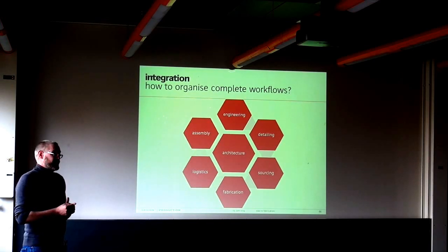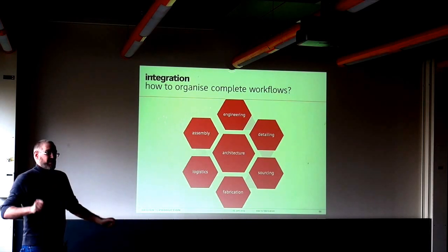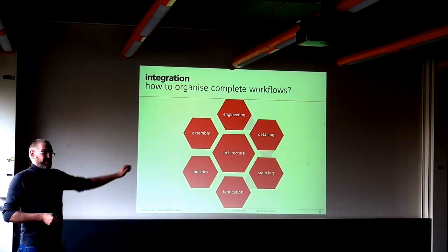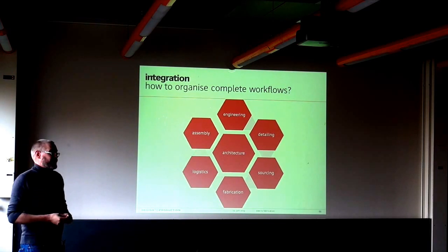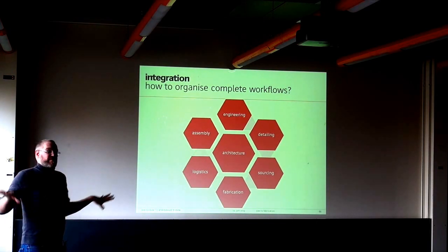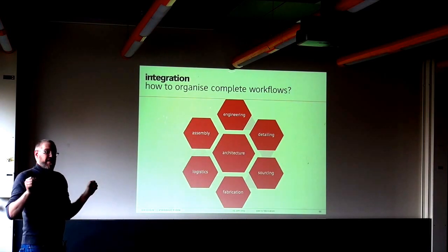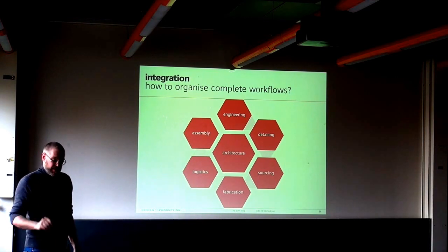The BIM world slowly is coming up with ideas in that direction, like the building collaboration format, where you have means of actually putting little sticky notes all over your model to say, hey, we have a collision there, hey, we have some problem there, who's going to resolve it? Just to have a management layer on top of the whole model that tells somebody who's in charge, oh, how many open issues do we have in the model? Not there yet.